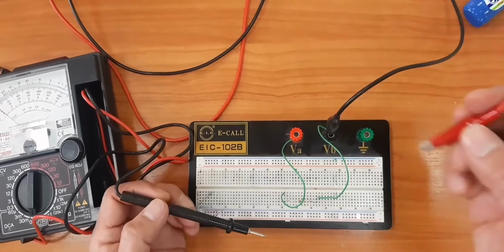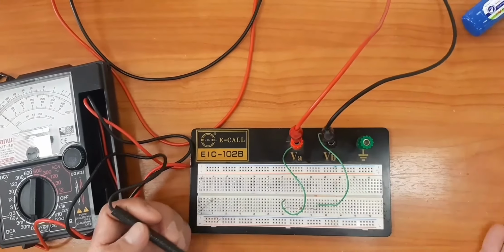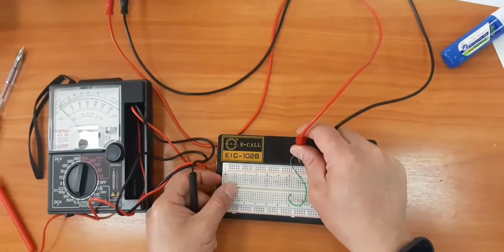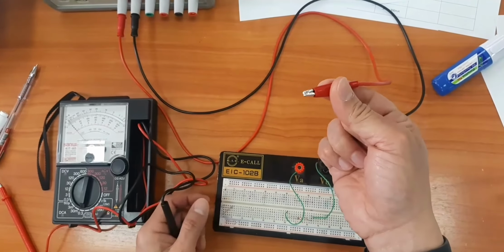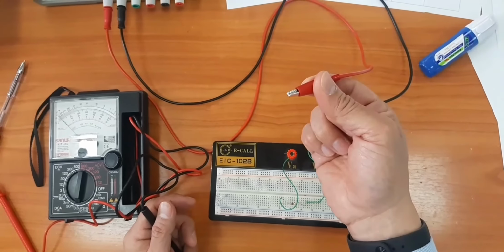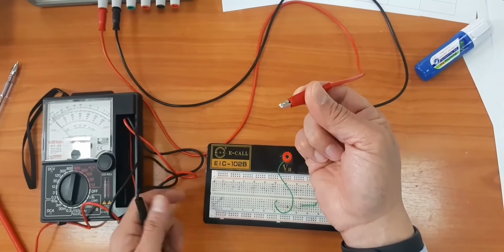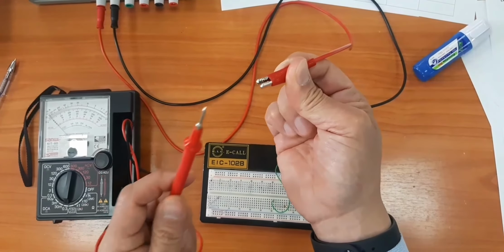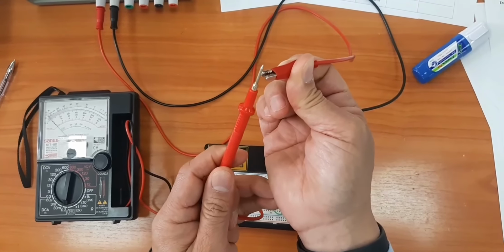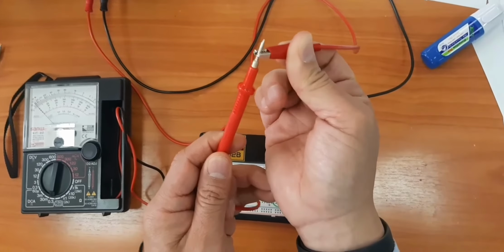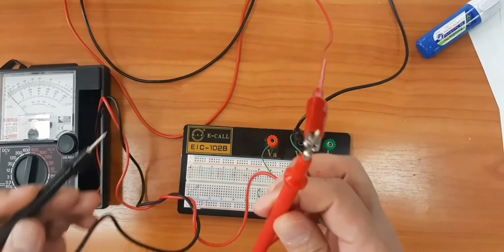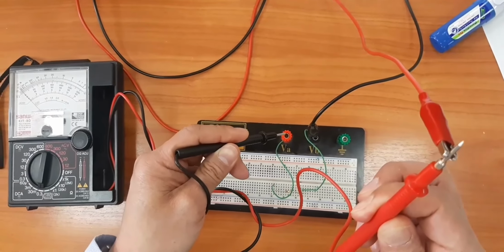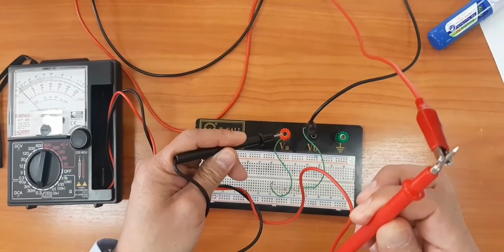Okay, again, if this is a complete circuit, you need to cut the circuit by removing the positive supply of the battery or power source, then connect this positive supply to the positive test probe, then connect the negative to the resistor where before the positive terminal was connected.